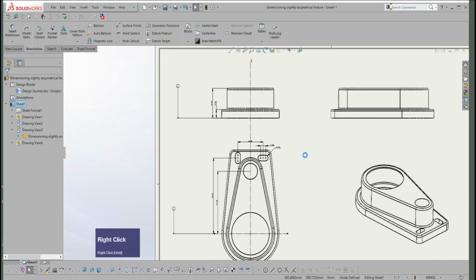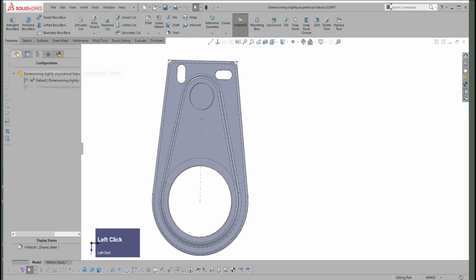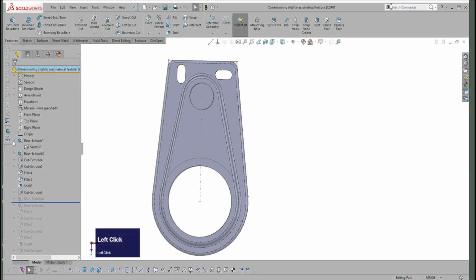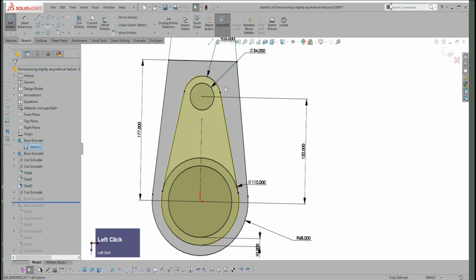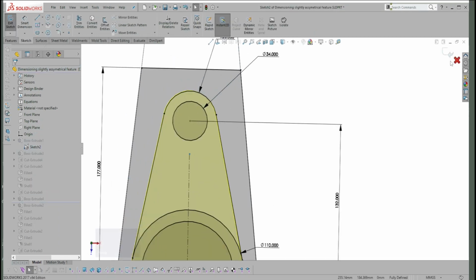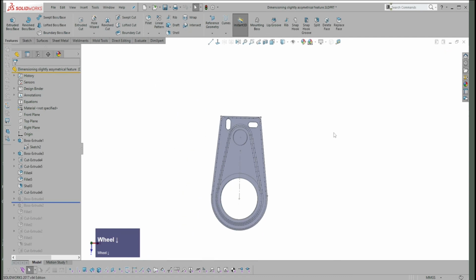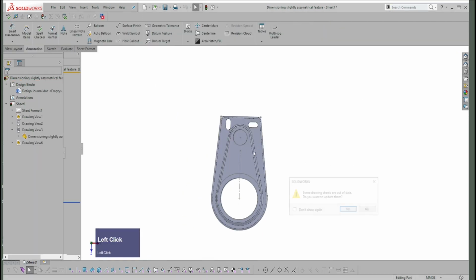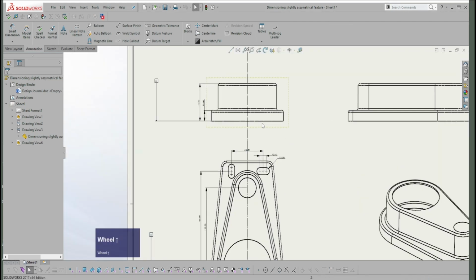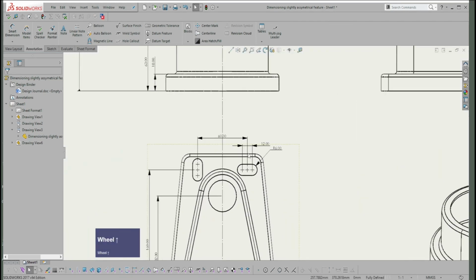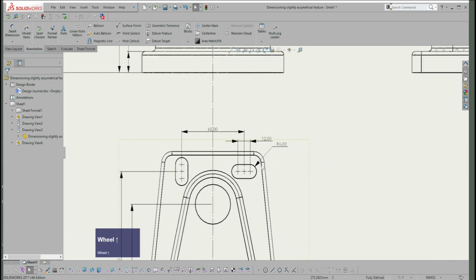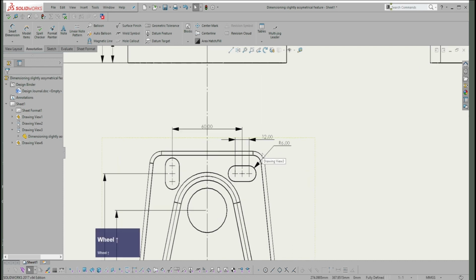If I go back to my model and have a look at the original sketch, you can see that those were 2 sharp corners, right? And that's how it would be made, using the geometry of this plane meeting that plane, not the center or the meeting point of two lines running parallel, which would indicate where the fillet starts. So the fillet is like, you should be getting rid of it in a way. So we can do that.